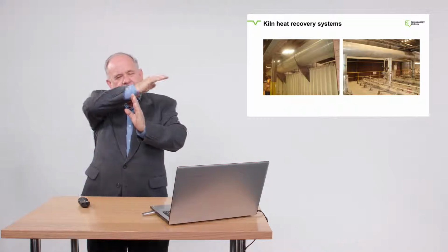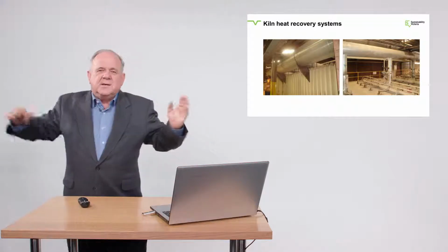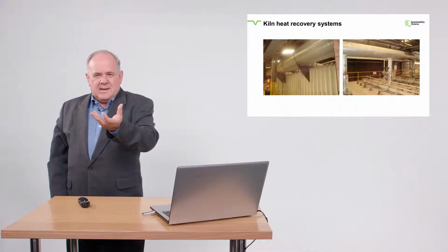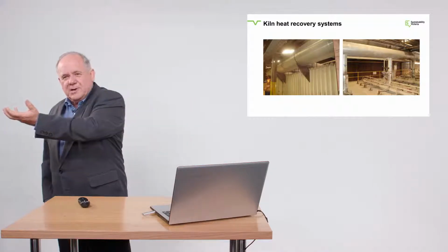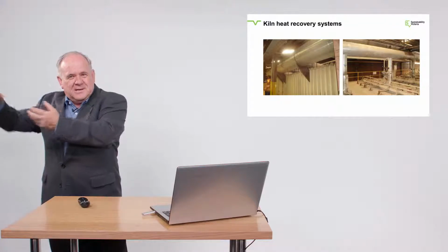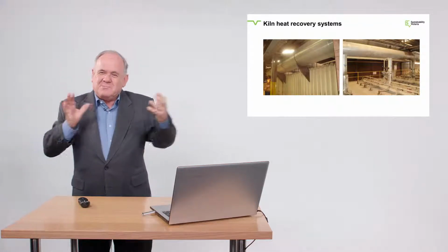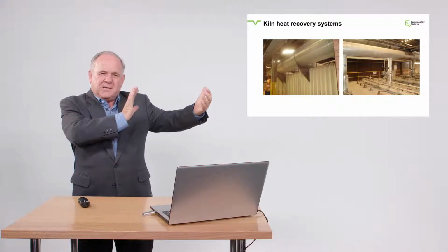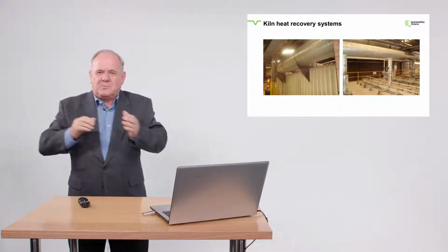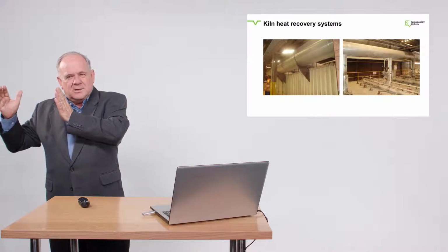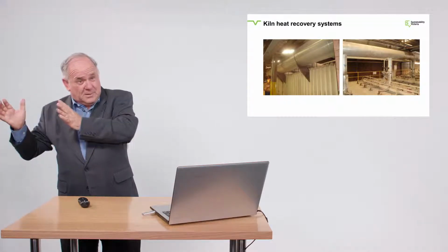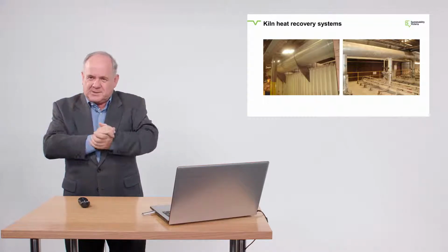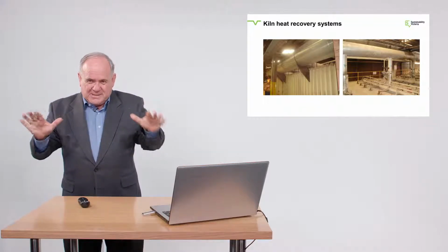So that airflow flowing counterflow to the bricks basically cools the bricks, preheats the air, and then finally preheats the bricks as it leaves. So a very simple process, but it has a massive impact on the energy because it's replacing energy that you would need to cool and replacing energy you'd need to preheat the brick, and also you've got preheated air for combustion. So that's your basic situation.